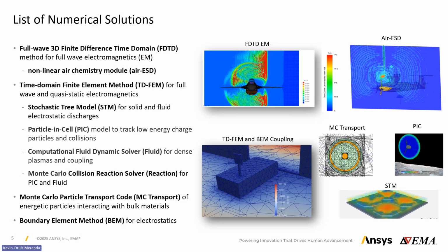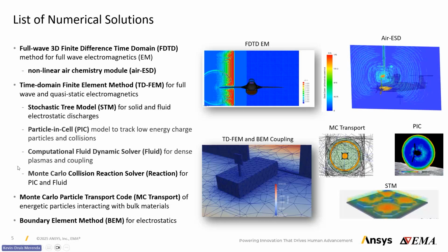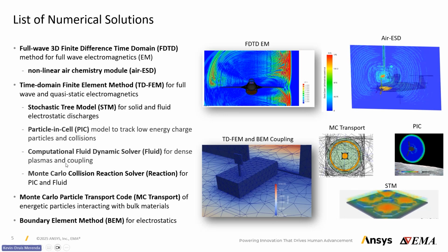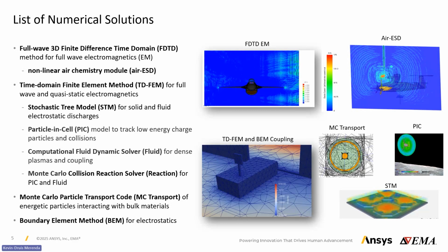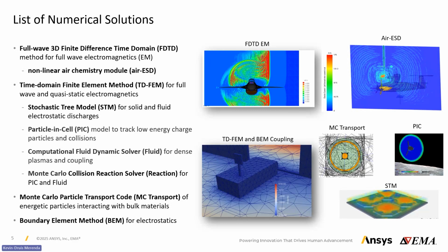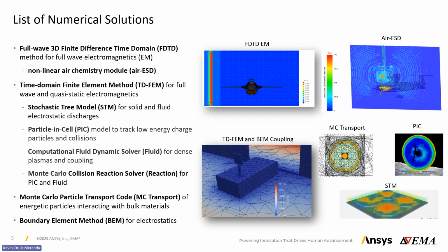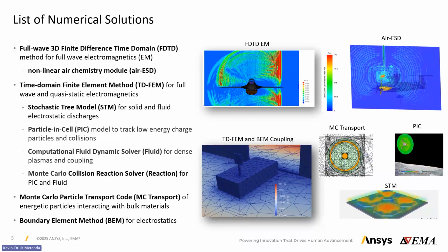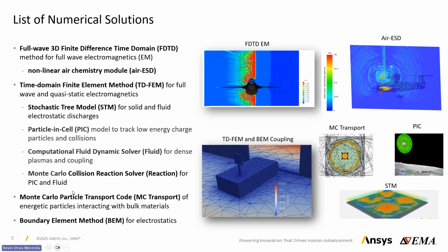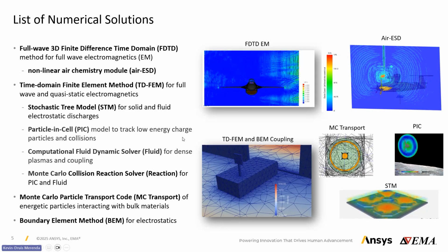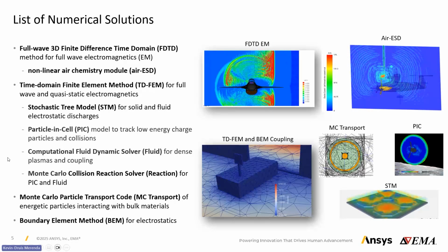And then if you don't know the dielectric strength, but you know a lot about the gas itself, like the reactions, ionization, dissociation, things like that, you can start leveraging the PIC, CFD, and Monte Carlo modules that we have. I'll show you various ways that we've used it to model discharges in nitrogen, in hydrogen, and you can also use them for argon simulation discharges, with a lot of various approaches. So much higher fidelity plasma modeling. Very computationally intensive, but probably the highest fidelity and most robust way to solve these problems with the fundamental principles.